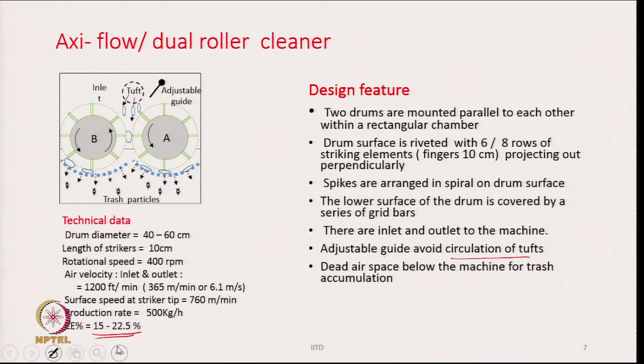The dead airspace below the machine is for trash accumulation. The machine is connected to a suction unit, and through the suction we are basically bringing the tufts into the machine and taking them out also.